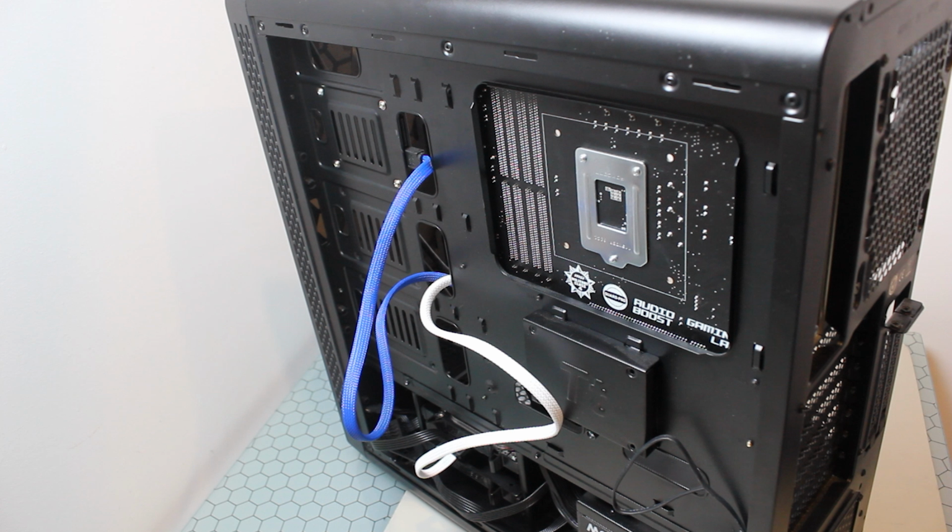You could also have run the cable on the other side of the backing plate, but this would have meant that the cable was running towards the motherboard. This would then mean that you would run the risk of the cable interfering with other components on the motherboard. So you can see sometimes it's a trade-off between having some bends in the cable or running the risk of having the cable get stuck in other components like fans.